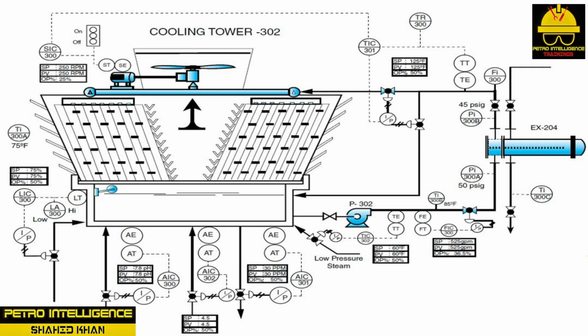The heat exchanger is comprised of stainless steel and is rated at 225 psig at 250 degrees Fahrenheit or 121.11 degrees Celsius on the tubes and 225 psig at 300 degrees Fahrenheit or 148.88 degrees Celsius on the shell. The inlet pressure on the tube side is run at 50 psig and 45 psig on the tube outlet. The tube delta pressure is 5 psig.